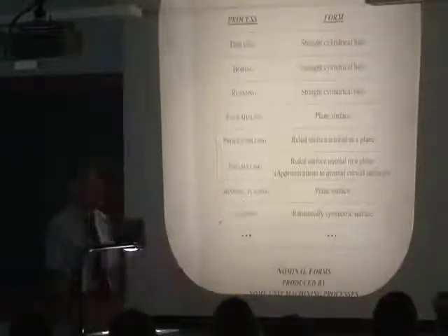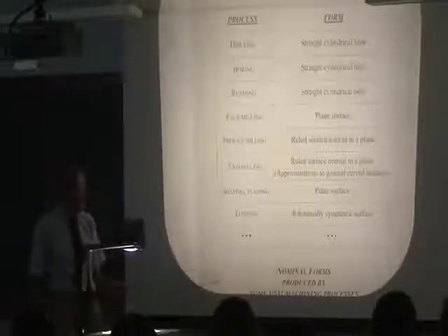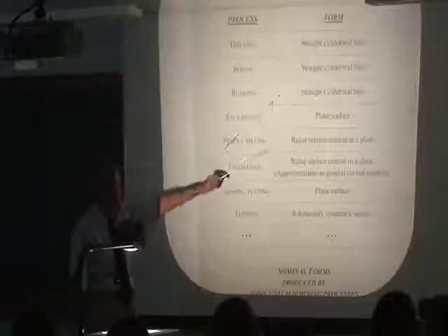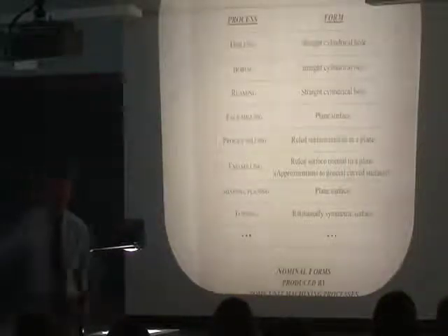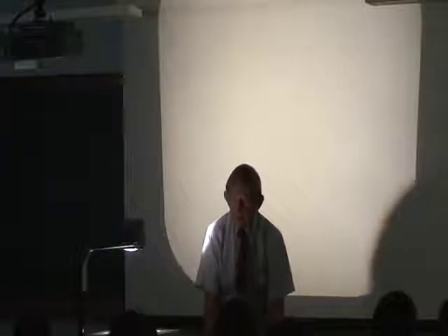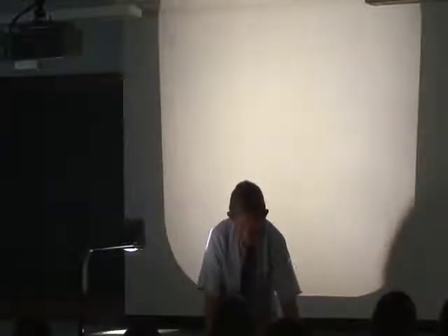Everything you make on a machine tool, every complicated shape, is made up of approximations using these pieces of surfaces, pieces of plane, pieces of cylindrical surface, and similar. Well, that's a gross shape. And the critical point now is how accurate is this stuff. As I've said, twist drills are really very imprecise cutters, which they are.